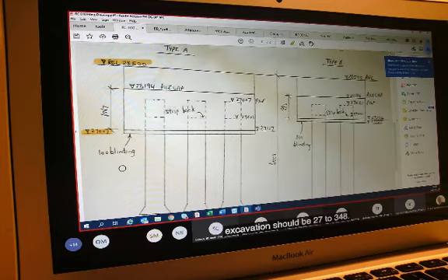Yes, because I think according to your specification on drawing 010, the bottom level of the excavation should be 27203 for type A, before the allowance of the landing layer, that is 100 millimeter.